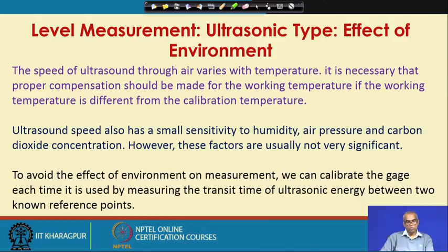So, every time I use the ultrasonic device, I can take two known reference points and find out the transit time of ultrasonic energy between these 2 points. That means, the time ultrasound takes to travel between these two known reference points. Two reference points whose distance we know exactly.